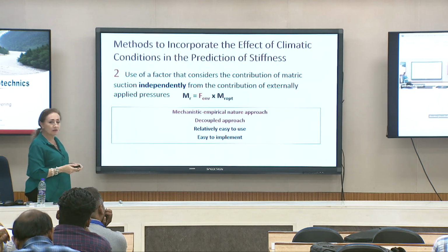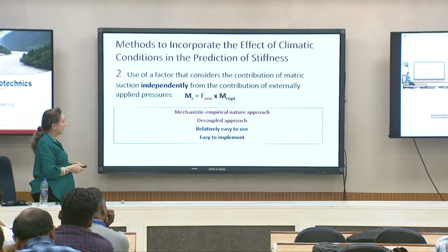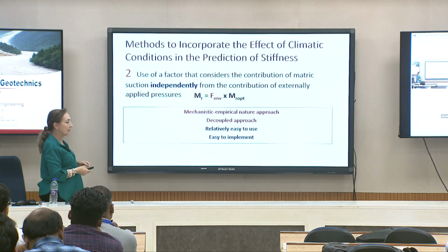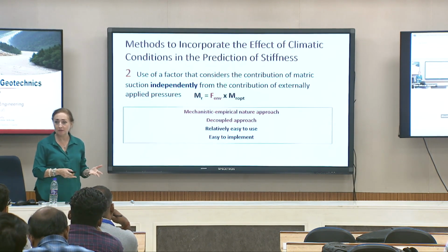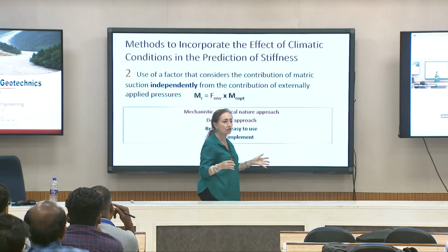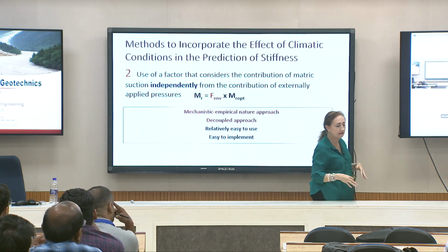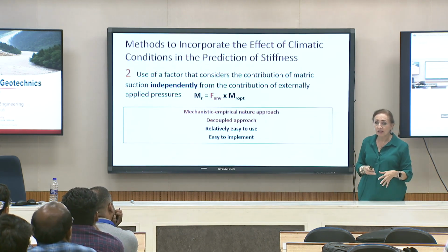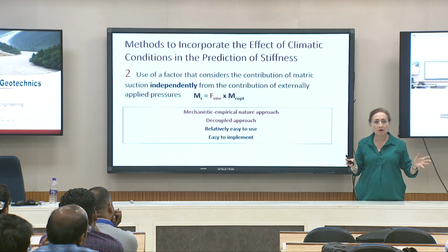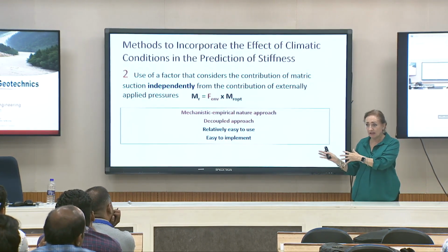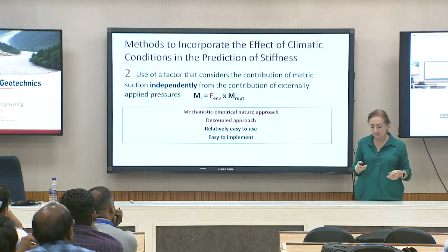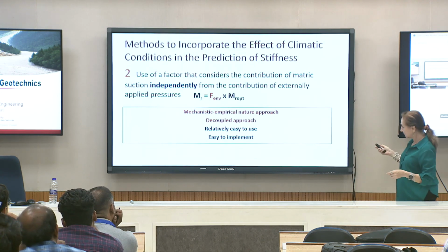But in order to get there, there are ways of doing it more empirically. You don't have to run Plaxis for that. And this is actually the way the AASHTO design guide, which is the latest design guide that we use, is doing it. They're not running Plaxis, they're not running finite element modeling, they're doing empirical modeling. And I brought this one because I know we have practitioners in here for railroads and also for pavements.